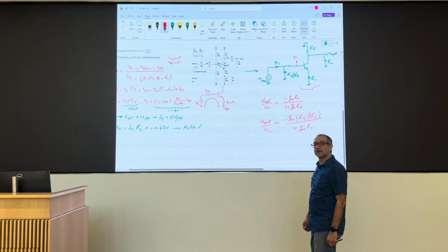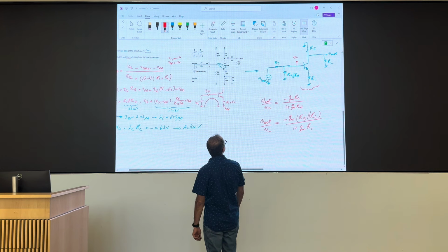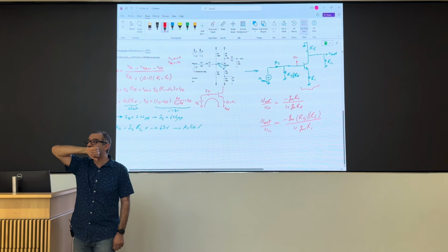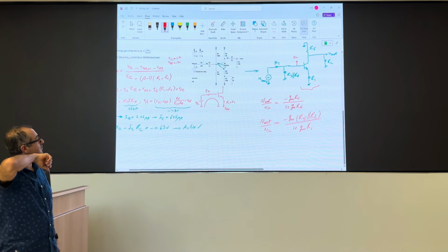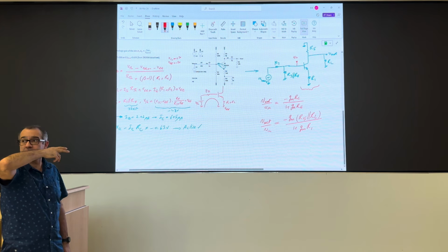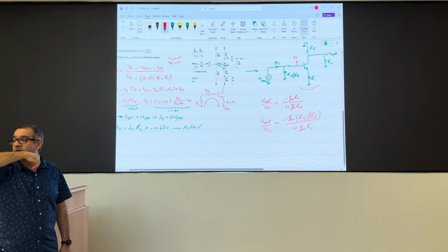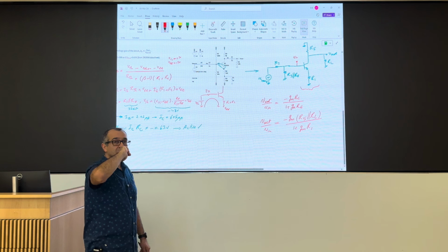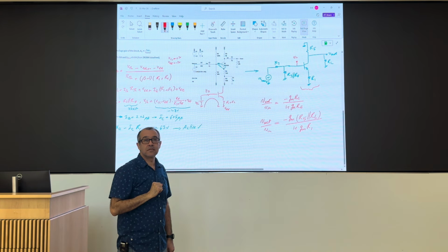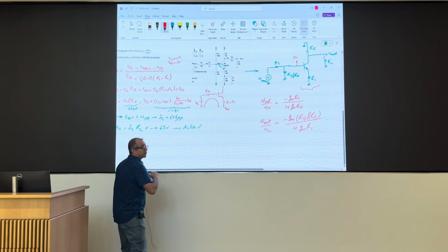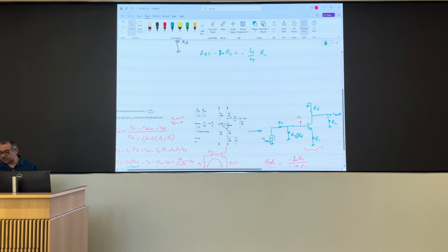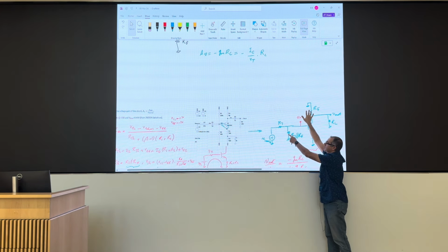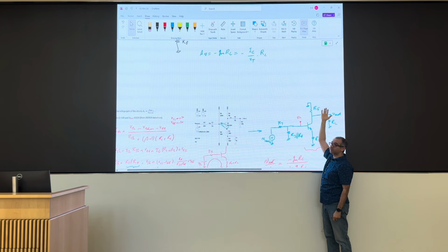Is it just across the R7? So V in, well, tell me. You could do voltage division from V source across R7, R3, R4. Then what about the transistor? Oh, right. It's loading that node. What do I do? See, if I didn't have the transistor, my life would be easy. If I just needed to find V in, if this guy wasn't here, that's just what you just said, right? Voltage division between these two. But now that I have this circuit, what do I do?